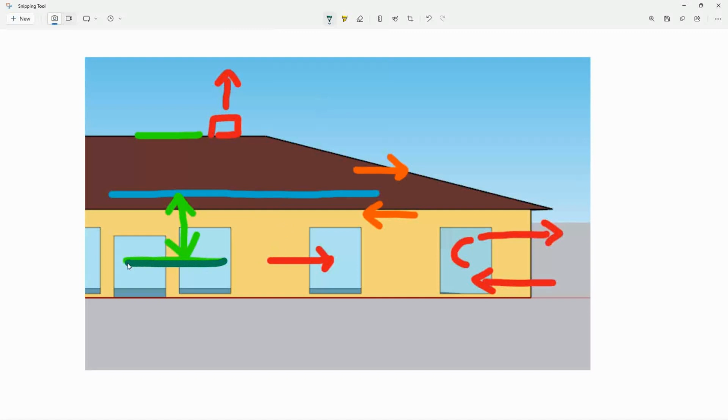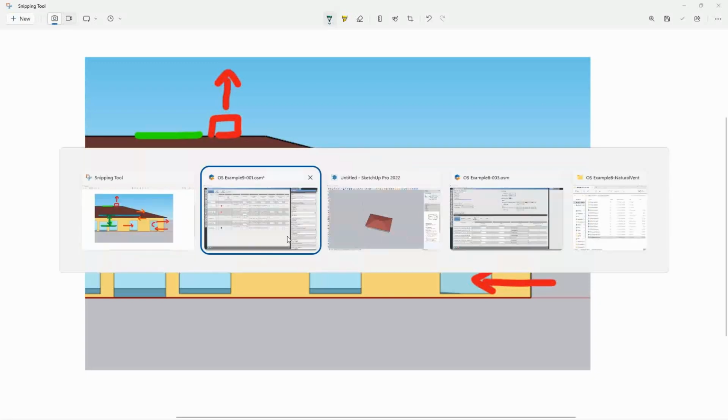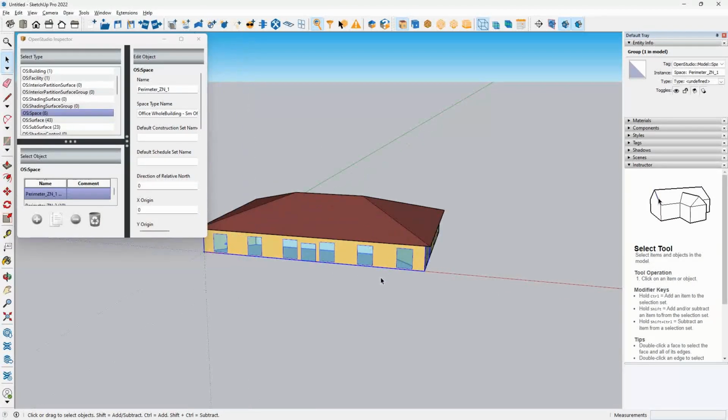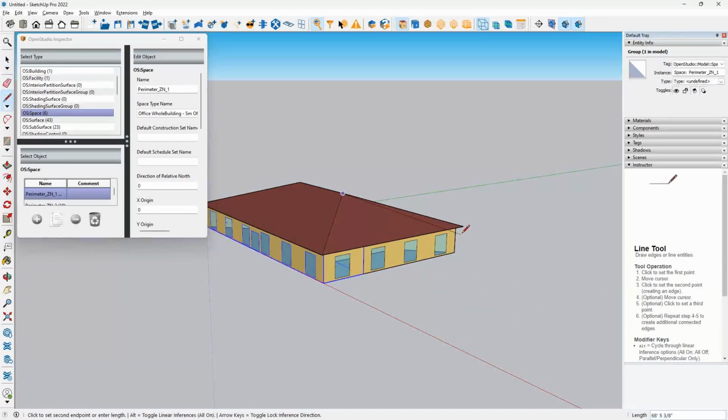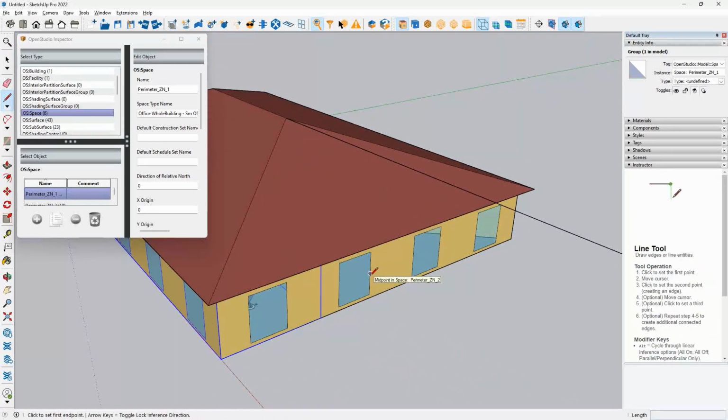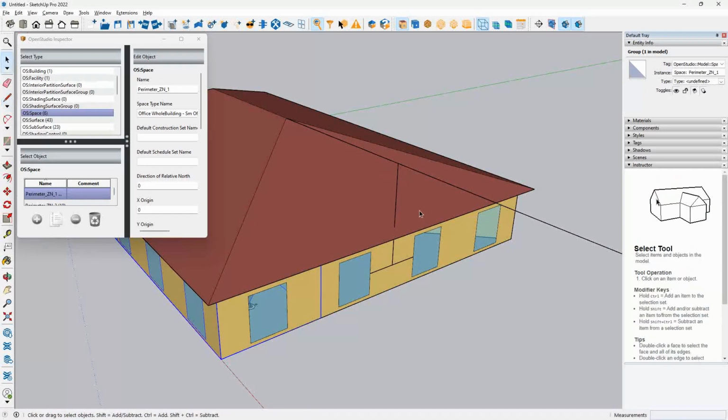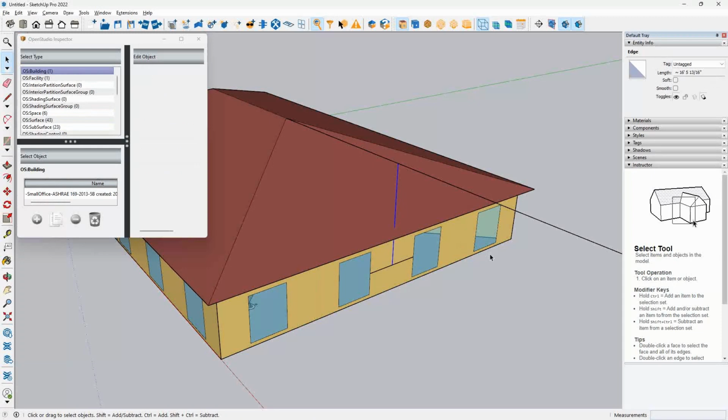the middle of the window and the neutral pressure level. So it's going to be this distance right here. That's what the height is. So we can calculate that using SketchUp. We're just going to extend this out, and we'll just draw a midpoint of the windows and draw this up there. So SketchUp is telling us that this line is 16 feet.